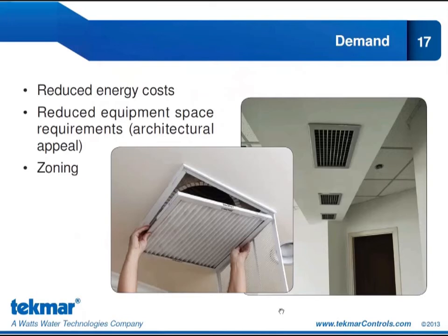And we saw earlier in the presentation that the heat capacity of water is nearly 3,500 times the heat capacity of air. So we are able to provide the thermal conditioning to a space using water at a fraction of the energy that it takes to provide that same conditioning using forced air alone.